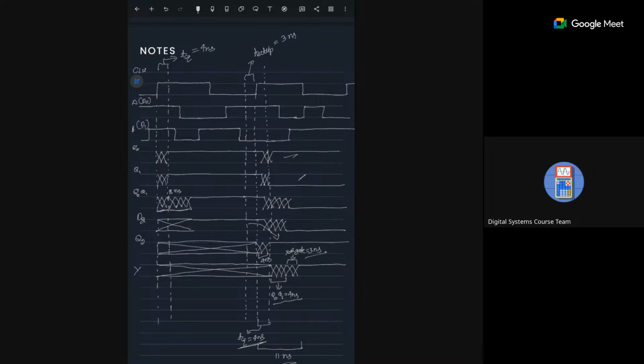Now we start with the 3 nanosecond, we are getting 18 nanosecond. We assume that 3 nanosecond is the starting point. So we are getting a 15 nanosecond delay. I think the question is a bit ambiguous because it doesn't say at which edge you need to calculate it. Because this total time is for the first clock edge, as defined from the clock signal representation. Is it at the first or at the second?